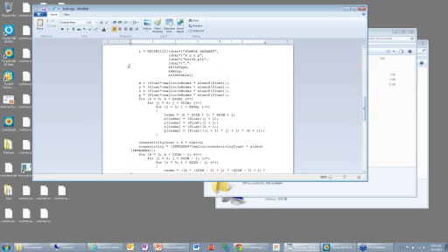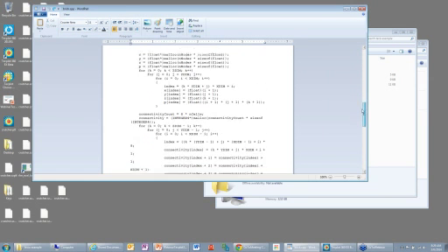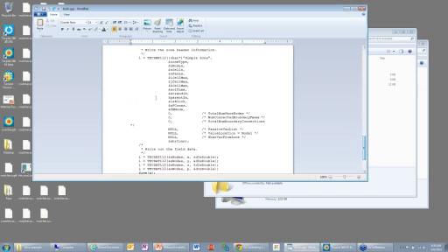But I wanted to show you the particular TecIO functions that were called to give you an idea of what it takes to create a Tecplot binary data file. First off, we call TecINI112 to pick a file name and enter the variable names and a few other things that are of less significance now that we're just setting up the data.